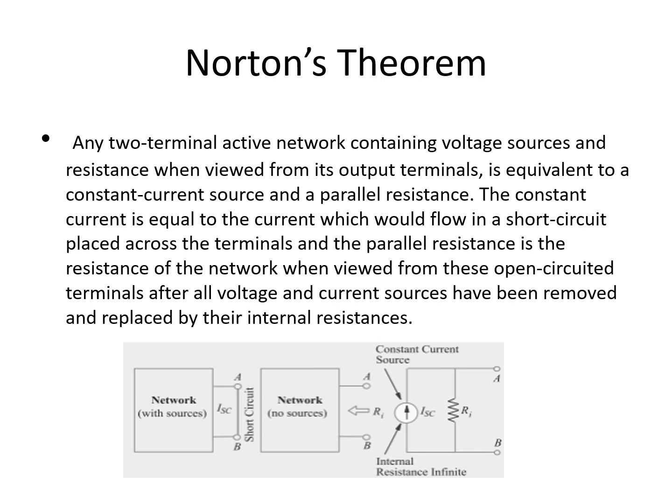What you're going to do is you short circuit that terminal. In Thevenin's, we open circuit the terminal. In Norton's, we short circuit it. So that's the first difference.